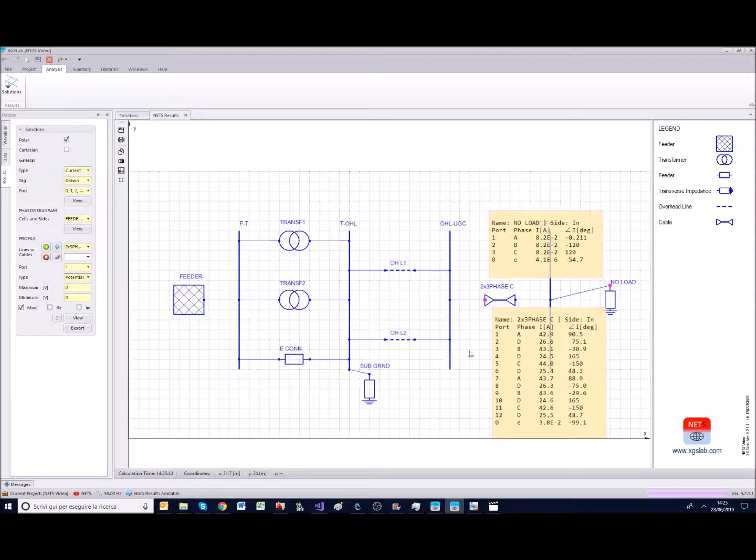Consider that basically these currents that you can see are due to the capacitive effects in the cable. Unless this effect you could not explain some currents with a no-load configuration. And also the phase can explain very easily that it is a capacitive current, since the current is 90 degrees before the phase of the voltage.